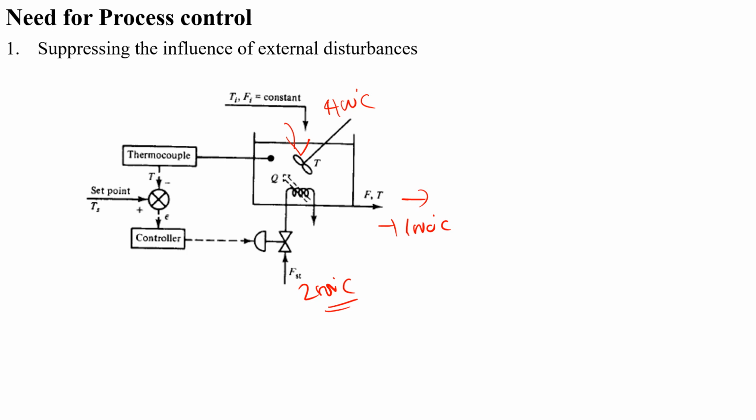So that has to be compared with the set value, say for example 1000 degrees Celsius. Then the error is given to a controller. The controller is a set of algorithms, so that will give the actuation value. So that actuation is acted upon this control valve. Then based on the actuation, the control valve will be opened fully or partially or shut. Then accordingly, the steam is entered in and it will regulate the temperature. So this is a continuous process. So this is a basic control system.